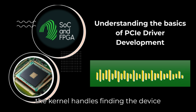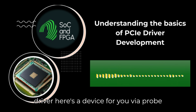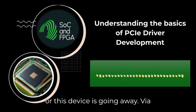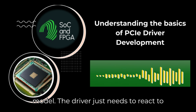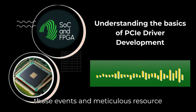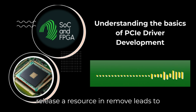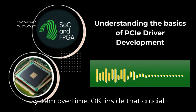So the kernel handles finding the device using the ID table and just tells your driver, here's a device for you via probe, or this device is going away via remove. Exactly. It's an event-driven model. The driver just needs to react to those events. And meticulous resource management in probe and remove is absolutely critical. Forgetting to release a resource in remove leads to leaks, which can destabilize the whole system over time.